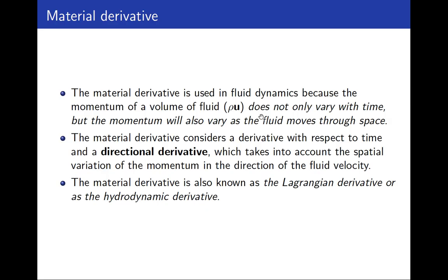So the momentum in a fluid will not only vary with time, the momentum will also vary as the fluid moves through space. So this derivative is important because we will consider two derivatives, one with respect to time and a directional derivative, which will take into account the spatial variation of the momentum in the direction of the fluid velocity.